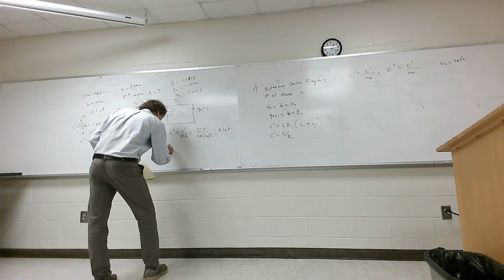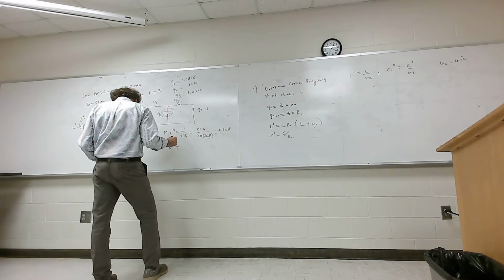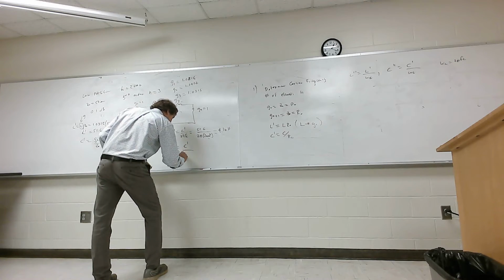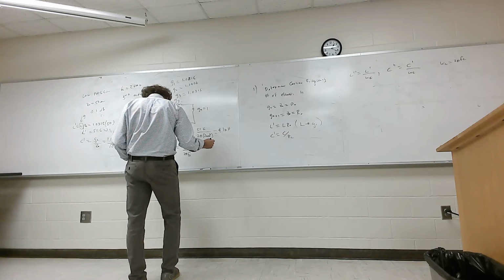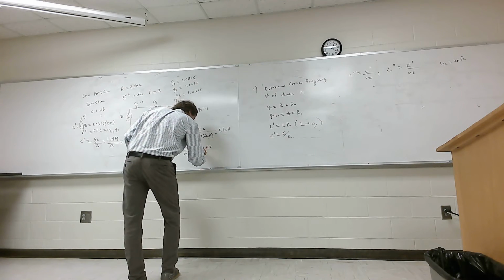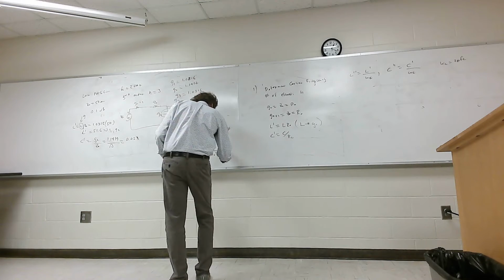And finally, the C double prime. These are the actual values that you want right here and here. C prime divided by 2 pi FC, that's 0.023 divided by 2 pi times 2 times 10 to the 9th, and that equals 1.8 picofarads.